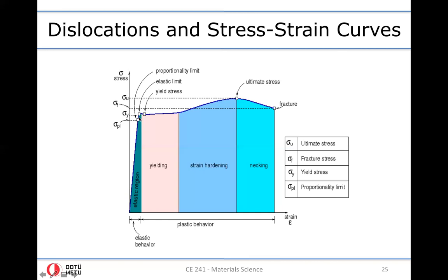But yield stress is the stress beyond which it's assumed that the plastic deformations are activated, and when you unload at a point beyond this point, you essentially unload elastically. That is the assumption, parallel to this line, and then the amount of strain that you observe here will be permanent strain, the plastic strain.